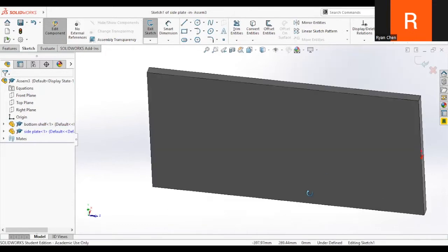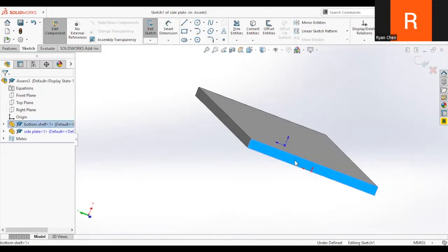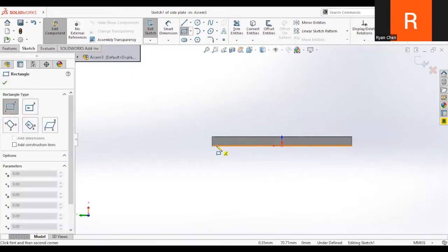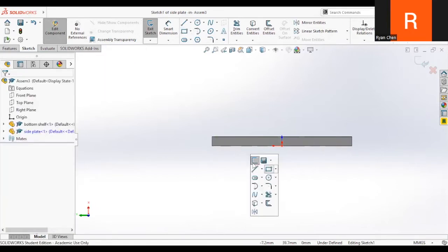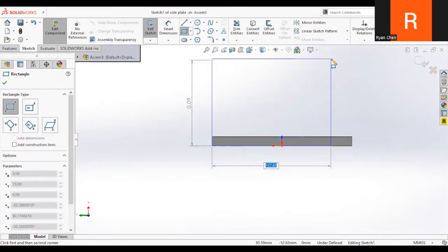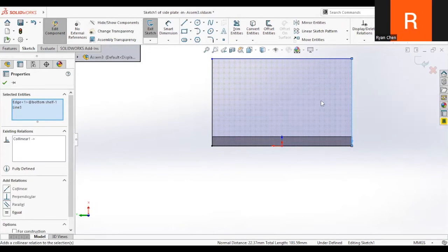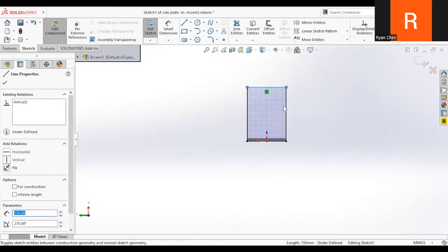Let me rotate it so it looks a bit more how we view it. And I will use a corner rectangle for this one. So the geometry does matter. This is kind of why it's called top down. You notice that I have to use the specific corner here. Make this collinear. It's a bunch of the normal sketch tools that you end up using.